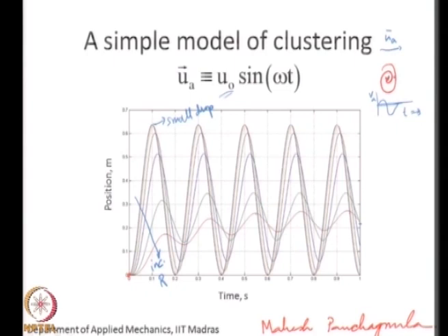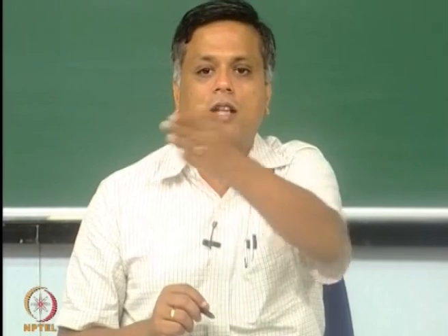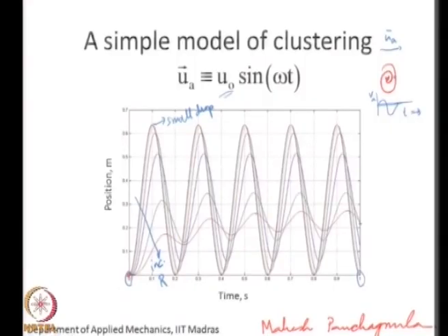Okay. So, if I look at the instantaneous positions of 4 or 5 different sizes of drops, some time later, let us say 1 second after I started this process, at time 0 all the drops were at x equal to 0. I subject this polydisperse collection, so I have 5 discrete sizes in this particular simulation, to this oscillating air field. Over 1 second of time, the larger drops have moved preferentially outward in relation to the smaller drops.